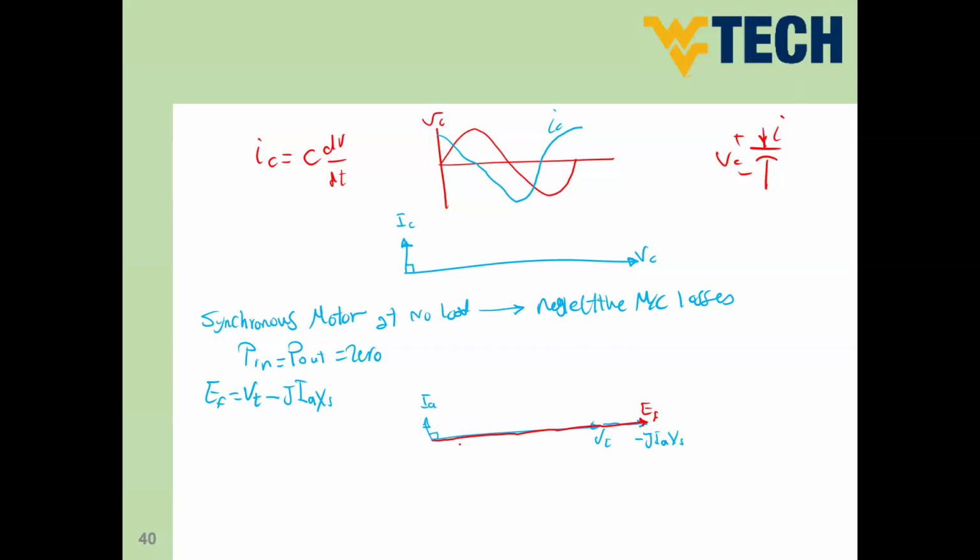What is the power angle here? Right, the power angle is the angle of the excitation voltage, which means power angle equals 0. And this is again the ideal case, because if power angle equals 0, this means the active power equals 0. And this is our assumption here. So it's an ideal case because the machine is working and we don't have any losses.